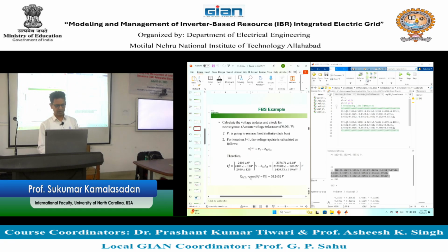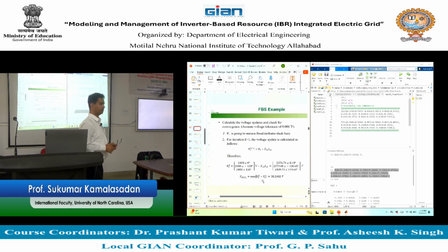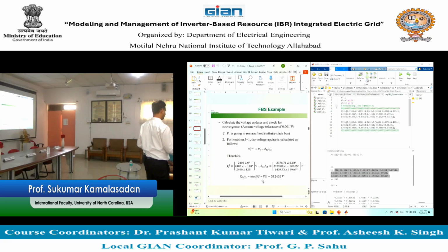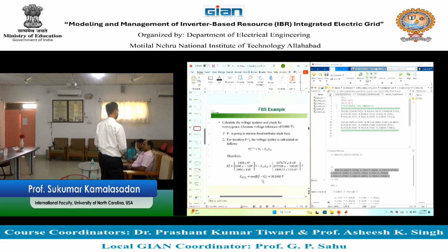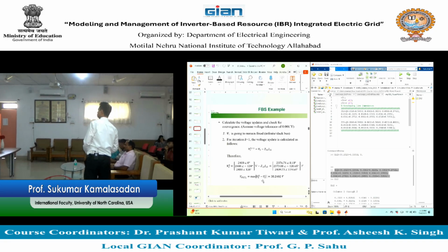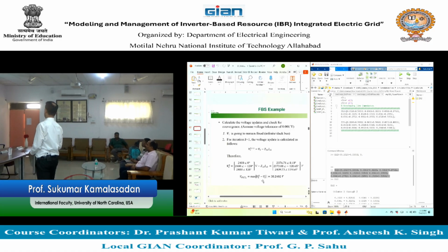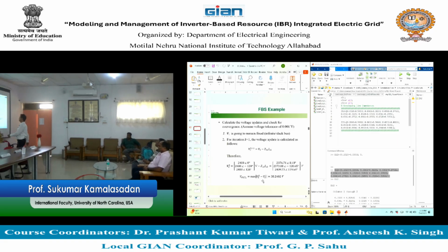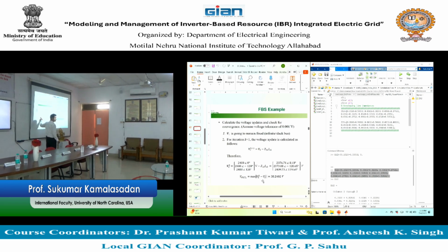now you are going to find out the difference between the V2 that you calculated first time and the V2 calculated next time. And that's basically your error, whatever you call it, error maximum. I have calculated V22 just above that line. So V2K plus 1 is V1 minus Z12 I12. I have calculated that. You did that? So the V2 that you calculated, V2K plus 1 is V22. The one you are calculating is this. Yeah, I have calculated that.